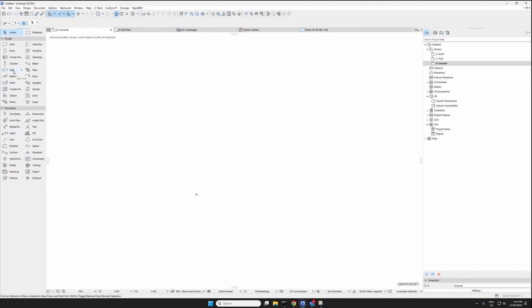So let's say we draw. In here we can draw something just by clicking the wall, and we'll draw a normal wall. We've got different types of wall we can draw up here. If I hold the button, it's going to give me different options: just a straight wall, a continuous wall, a wall that is taken from different points. So let's say I want a continuous wall.